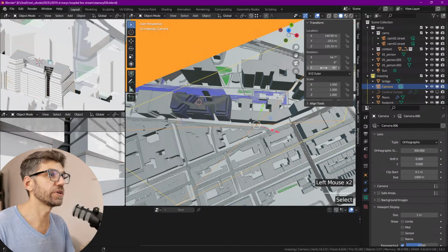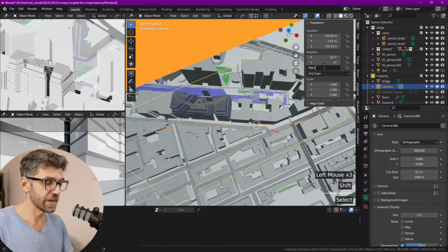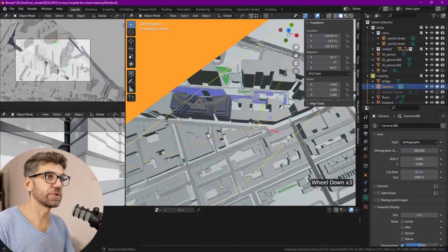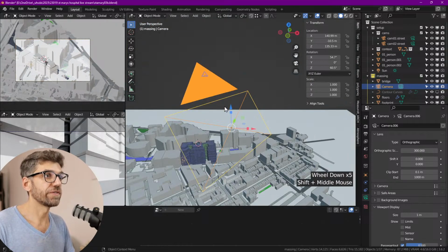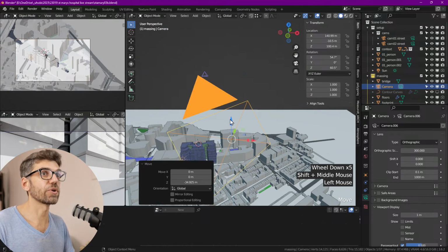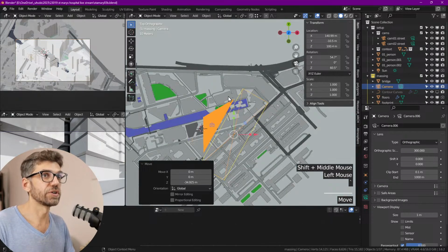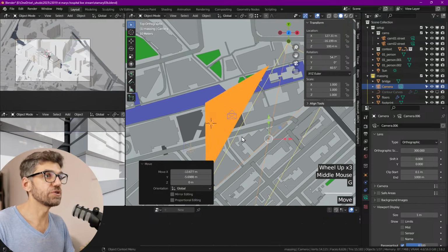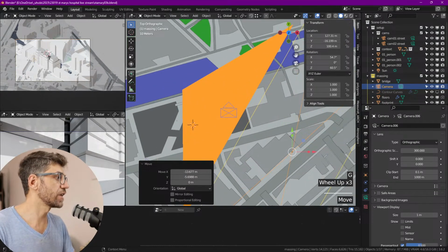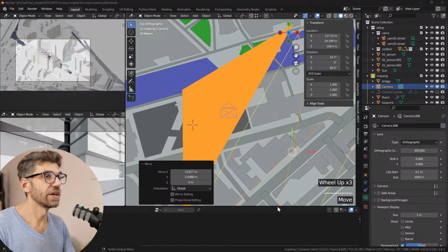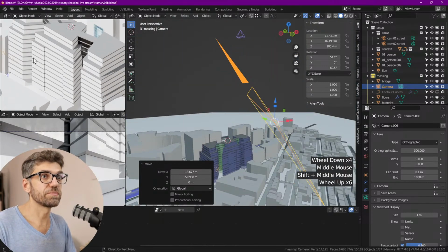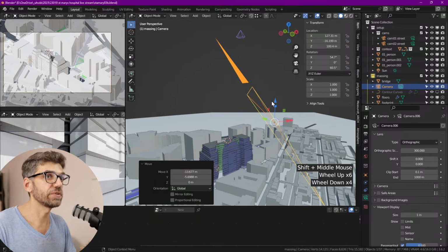So all we need to do in here is change the Z of 45 plus 15.5 degrees. So now it's a perfect isometric file, which, you know, in a program like Affinity Designer or Illustrator, you can go in there and continue to change this and have everything snap in the correct way for us. Okay, so now we've got this view that's basically set up, and it's an important view because we'll keep reusing this and recycling it.